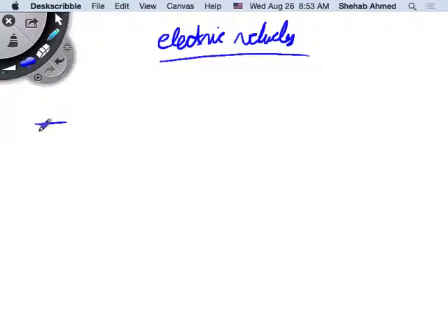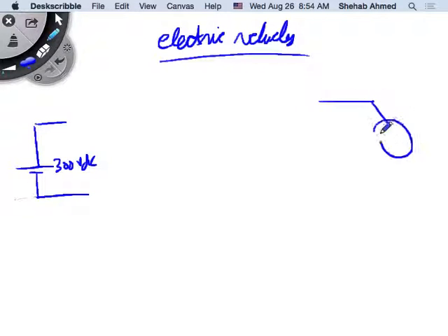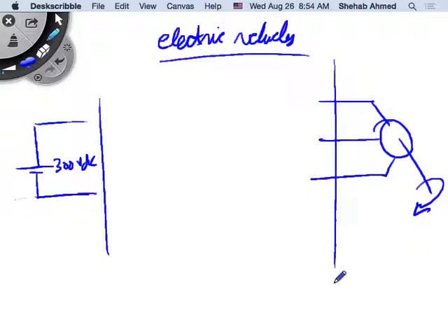So another application, electric vehicles. You have, typically in an electric vehicle, maybe a battery that's about 300 volts DC. And then what sort of load do you have in that case? In an electric vehicle, you have a motor type load, and it's typically a three-phase type motor. So three-phase motor. So this is your input, and this is your output. Motor voltage, maybe, I don't know, 400 volts or 300 volts. AC. So it's an AC voltage, yeah. All motors that are used in electric vehicles would be AC.